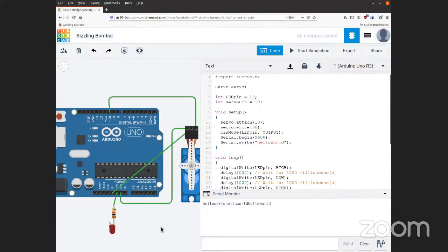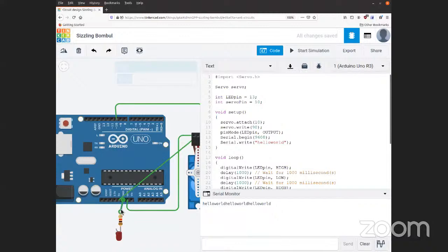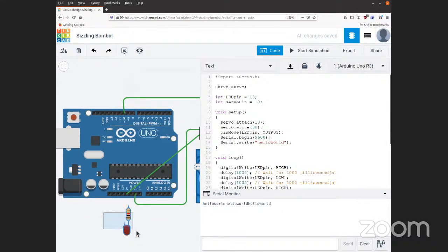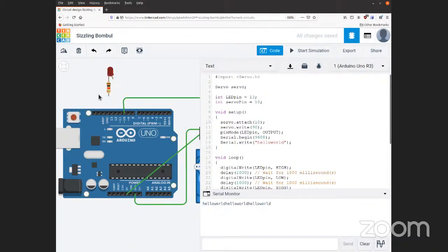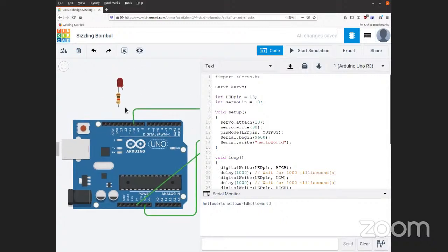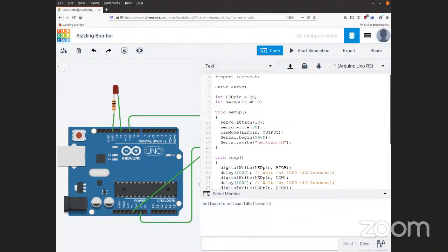So we could have also taken that LED that's on the bottom of the board, flipped it to the top of the board, and put it on pin 12, for example. Now you still have to have that ground coming to a ground, but then you could control that external LED using code. Yeah, exactly. I did not know how to rotate, so I'm glad you taught me that. And the reason we put a resistor in there, if that wasn't obvious, is that you want to limit the amount of current. LEDs don't really have much resistance, so without a resistor you essentially get infinite current.